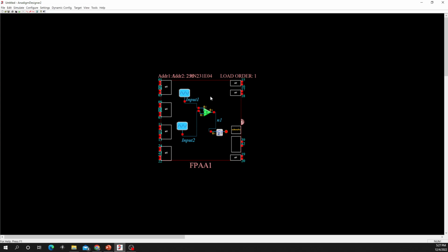Like what I taught you last time, you can use the oscilloscope probe to check the results. You can do it in different ways. One way is to right click with your mouse and say create oscilloscope probe, and you have one. Let's say you put one here. Another way is from here, there is a little tiny probe symbol next to it. If you click it, it gives you another oscilloscope probe.